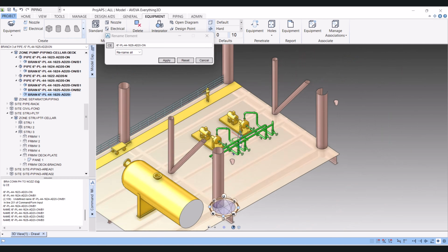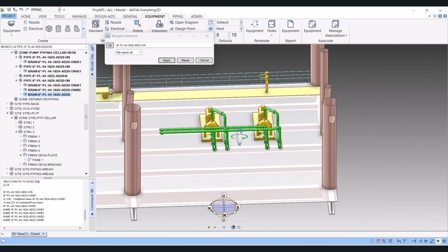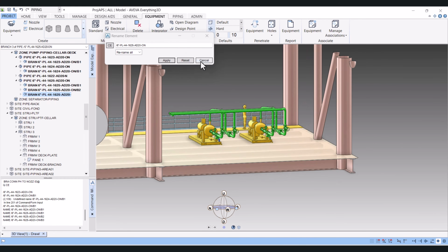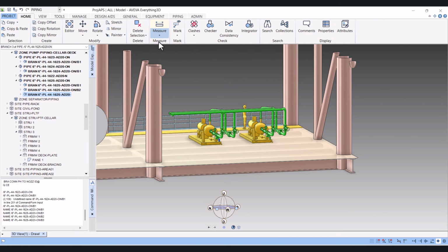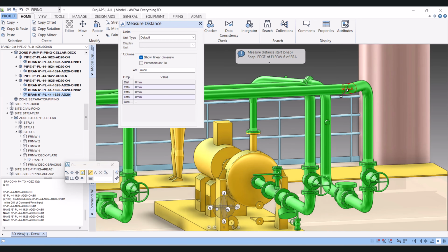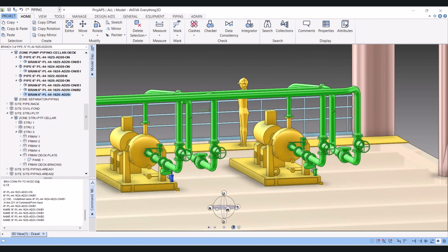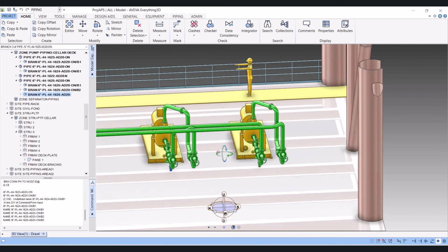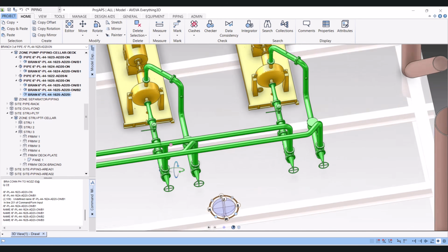So what we have to do while doing the piping here, we have to clear the main head. So let's see if it is clear or not. So we will click on Home and we will measure. This time we will select snap here and BOP. Here it is 3 meters, so in 3 meters we can cross easily without hitting the pipe.